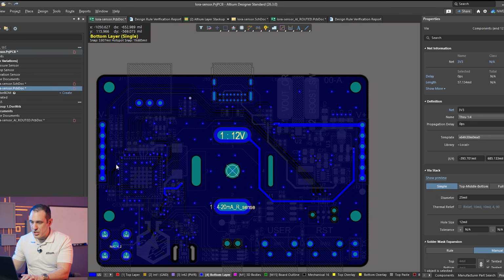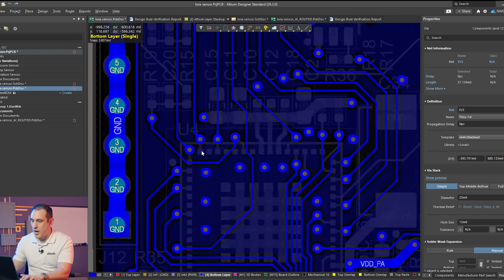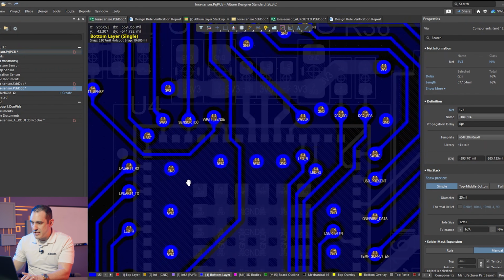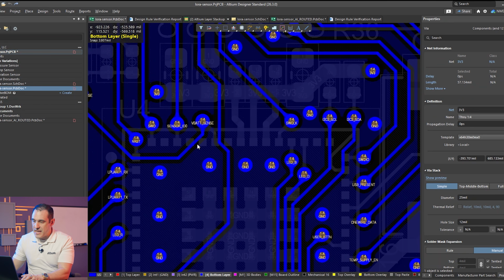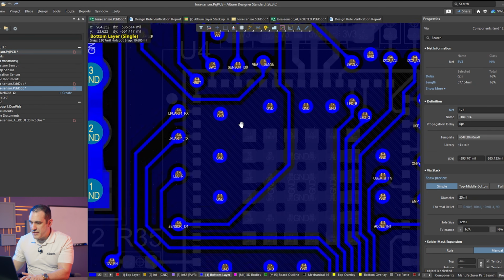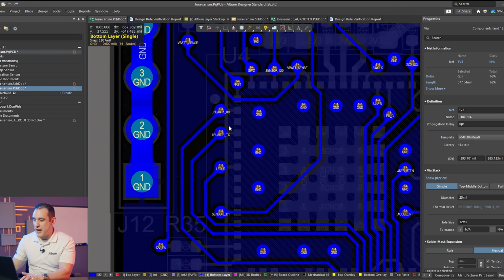You do have stitching vias nearby a lot of these signals as they traverse from the bottom layer to the top layer, and that does help to maintain signal integrity by maintaining a return path, and then it also does help suppress emissions. Also, some of these lines, as you can see here, are basically just DC lines, for example, this battery sense line. Some of them are also very low speed lines, such as these UART lines, and so they aren't really going to create a lot of risk of emissions anyways.